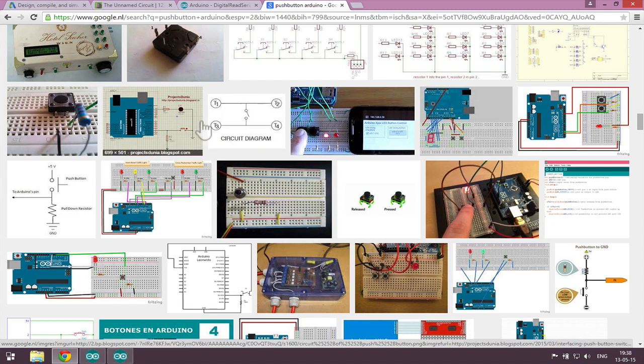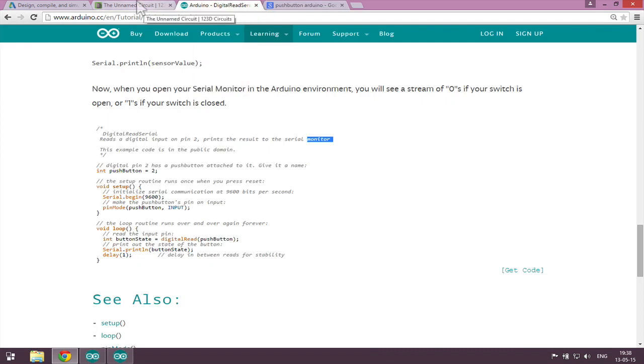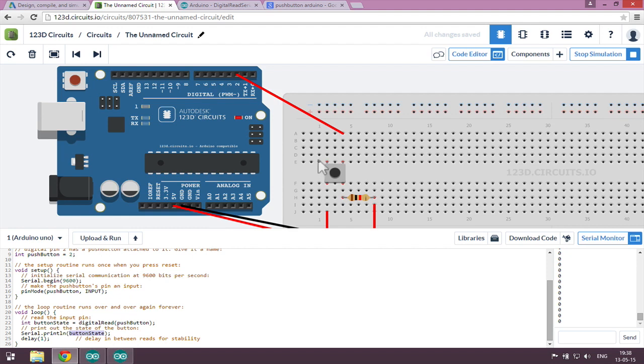So these two are connected, and when you press the button, everything is connected in an H form. So I hope this explains a little bit about how this push button works. In the beginning it's a bit confusing, because it's not a normal button. These two, this one and this one, are connected whether I press it or not. And this one is also connected whether I press it or not. When I press the button, everything is connected with each other.